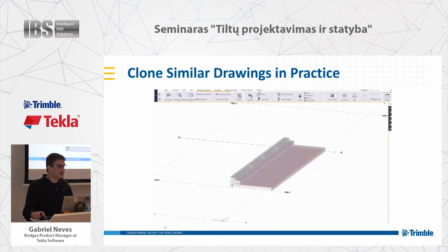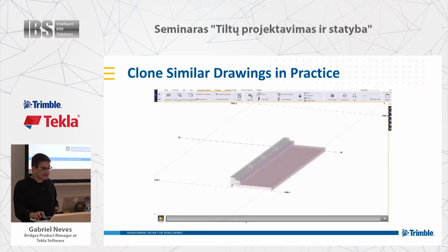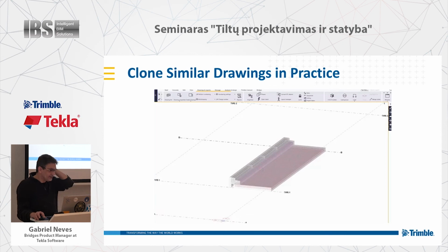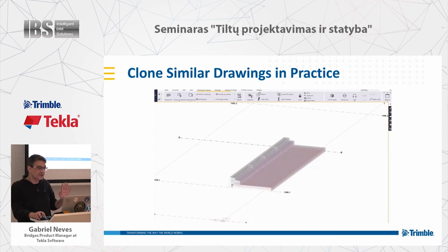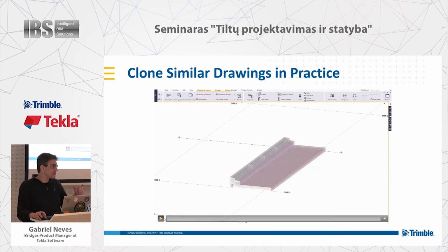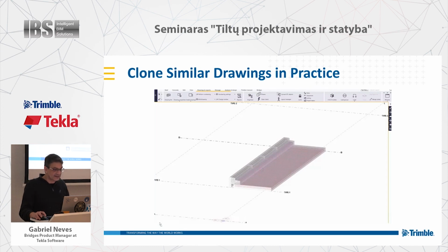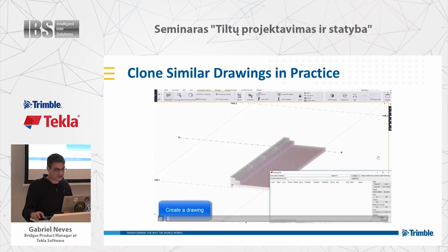So for non-Tekla users, this is one of my approach slabs. And for every approach slab, we were creating the drawing from scratch. I developed some settings, yes. Okay, right click and you'll see. Right click and we have some settings as a starting point, which is a good start, but all the rest was manual. And this is just an approach slab. Now you can imagine the wing walls and the portico and all that. But this is a small video just showing that workflow.